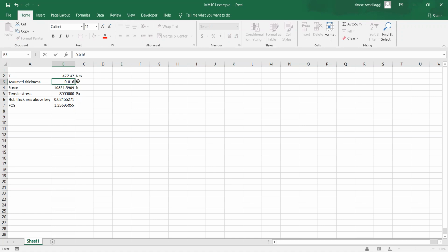All right, so let's press enter, and we see that we have this force that will be acting. Using the same calculation that we just did, it'll calculate the force for us, and it'll give us a recommended thickness of 29.7 millimeters. So it's saying 16 isn't enough. You need to use 29 millimeters if you're going to have this kind of force. But your factor of safety will be 0.5 if you use this thickness, 16 millimeters. 0.5 is less than 1, and that's not what we want.